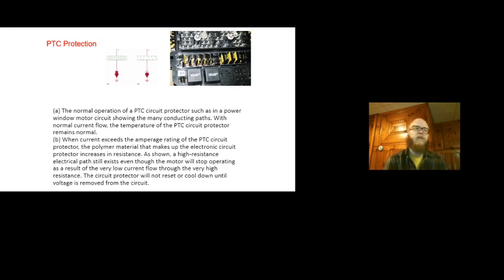What do we all do? You roll up the power window, and then you want to make sure it's really rolled up, so you pull up on the switch a few more times, or maybe you're like, I'm going to have a power window race, and you try to roll them all up at the same time and see which one gets to the top first. But when one gets to the top, you don't let go of the switch. And so that circuit basically becomes a short at that point.